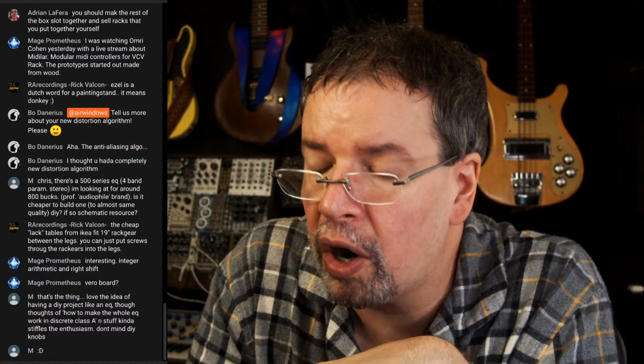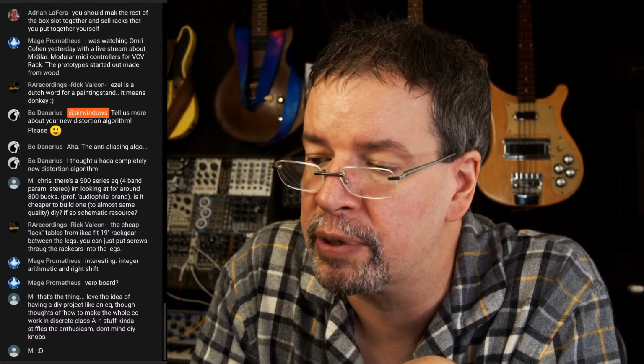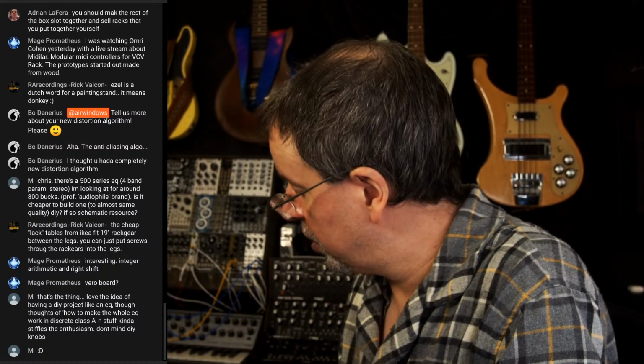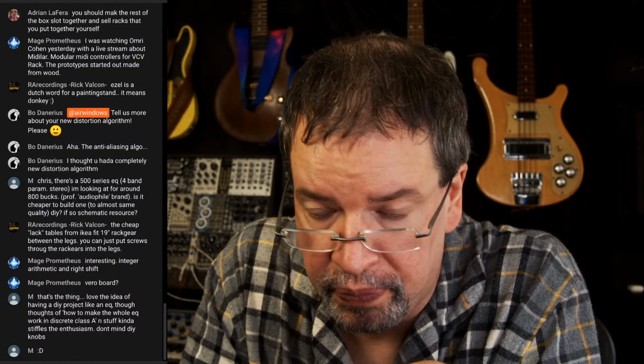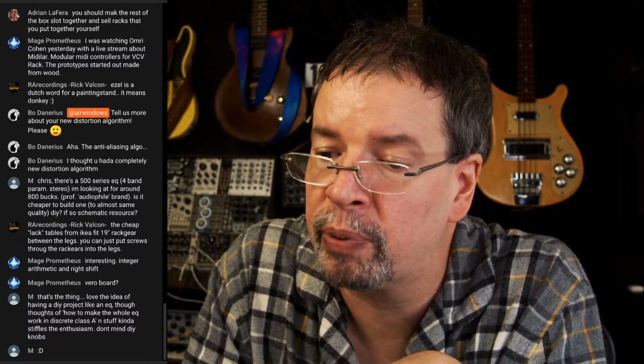And then if you wanted to go even farther, there are op amps that you can get that are plug-in replacements for existing op amps. So you can design with the cheap ones and then go for this later. You can get plug-in replacement op amps made with discrete parts. I don't think I have a good example for how I could show this. Instead of having the little chip that plugs into the DIP socket, there is a sort of a riser and this funny little circuit board that's like 3 times the size of what the chip would be. So you have to be able to fit it in there.